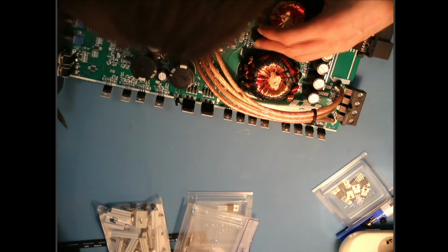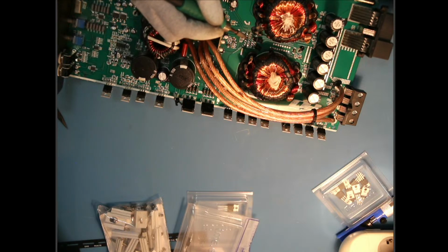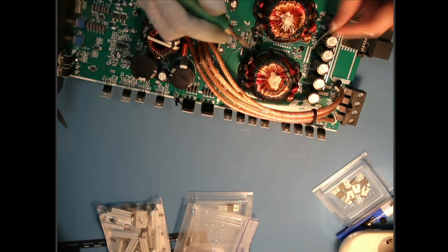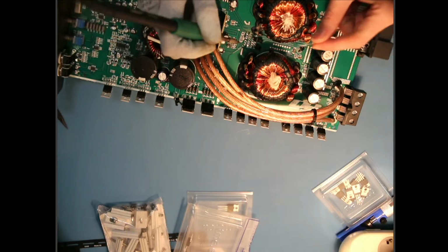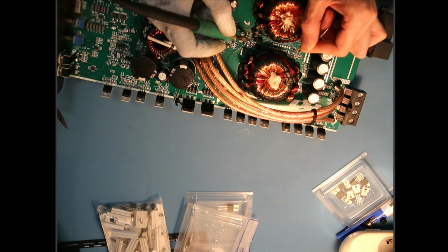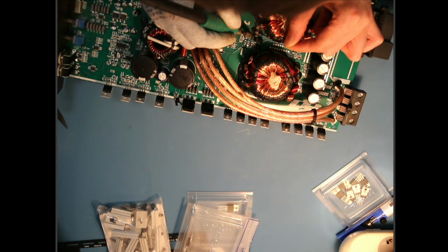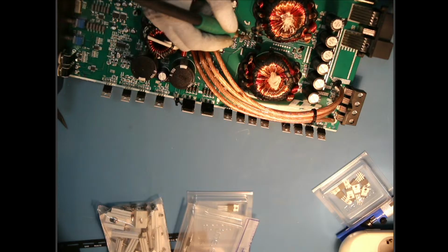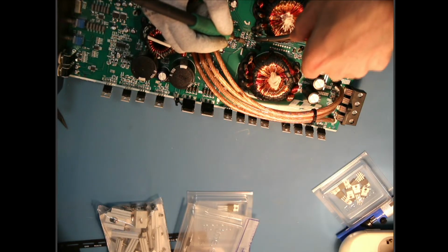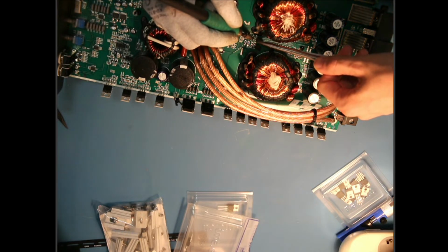This is 2SA, right? And the outer ones are 2SC. Just making sure. You know, you can replace an NPN transistor with a PNP transistor. You just have to reverse collector and emitter, and obviously the polarity of the driving signal and the reference, and the main supply voltage plus and minus. You swap them around.